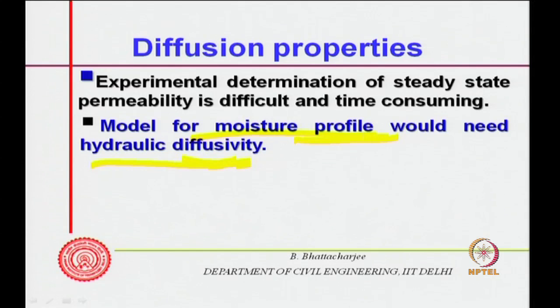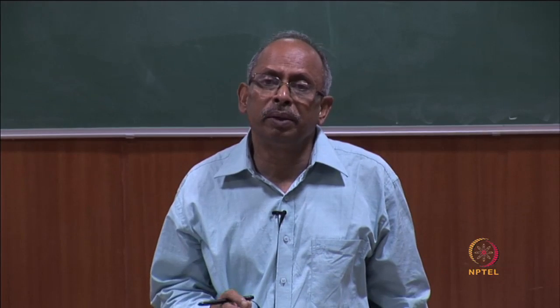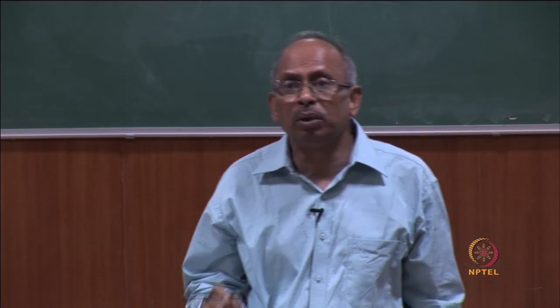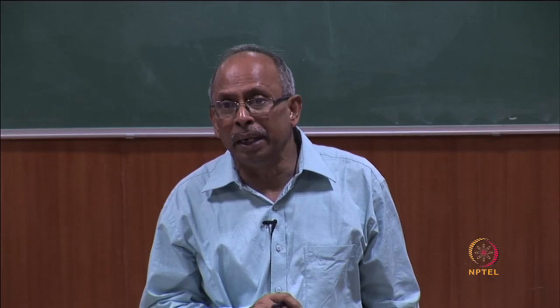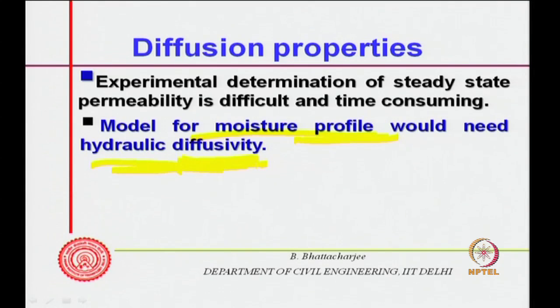So, diffusion properties are diffusivity, although they are not necessarily diffusion as we understood from Fick's law, that is concentration dependent diffusion, which is a function of the concentration because of the concentration gradient. But here the diffusion of oxygen, carbon dioxide, all this, they will be concentration dependent, but water diffusion or hydraulic diffusivity, it is not exactly diffusion, but it flows under capillary suction or under vapor pressure gradient. So, for water situation, hydraulic diffusivity one can use,